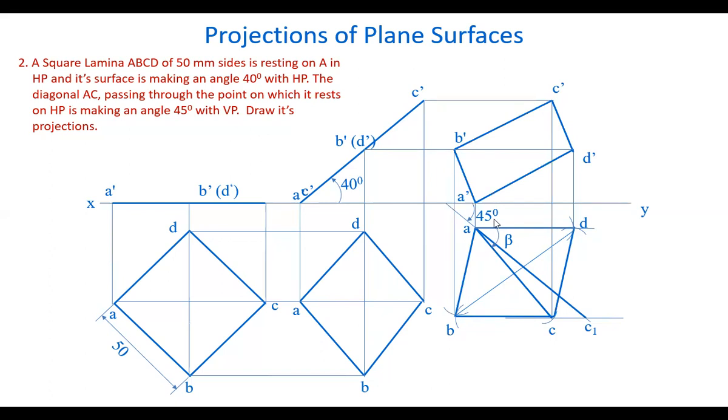One is we have to get the apparent angle, and on this apparent angle, you have to reproduce the same top view. That care should be taken. And first of all, you have to identify whether the given angle is a true inclination or an apparent angle. Okay. So these are the final projections of the plane surface when these 2 angles are true inclinations.